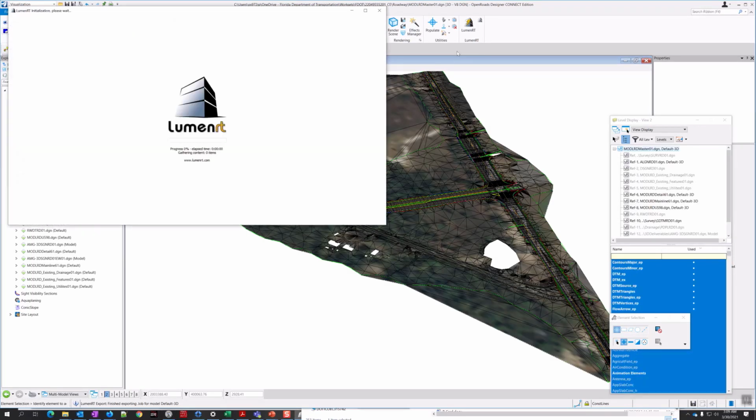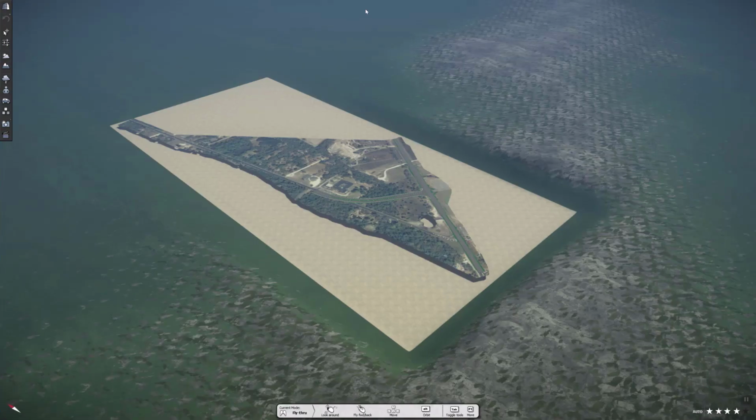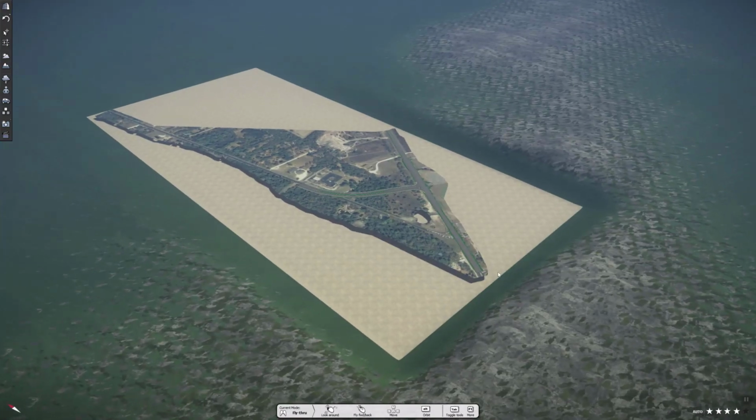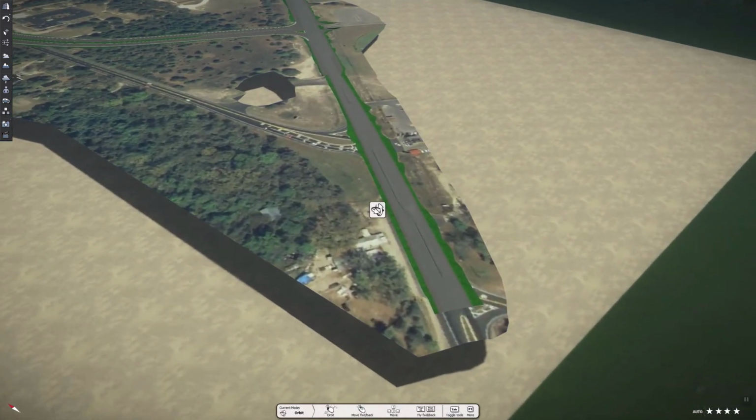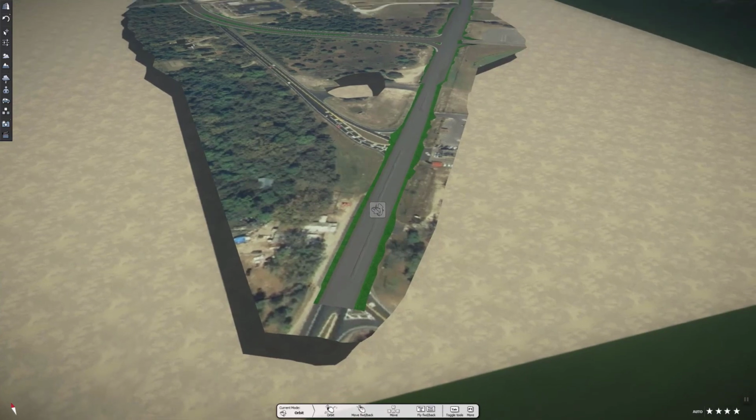We've got a decent graphics card on the machine I'm running this on, so even with that, it's taking a little bit to run, as you can see. So it'll open up LumenRT, and then LumenRT will go through the progress, and it's doing some more processing there. Alright, so there we have it, and so far it looks better. So I think turning off those levels probably helped make sure it knew what to do.